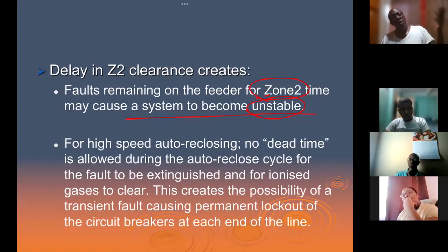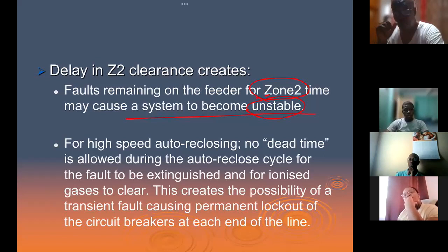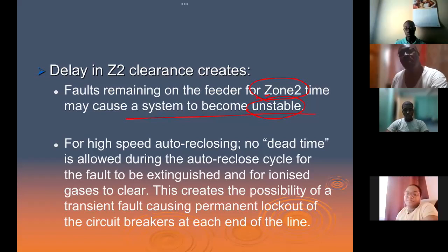So it triggers, operates, opens your breaker, but the auto recloser will seek to reconnect the system without human intervention. All right? So that's how the auto recloser operates.